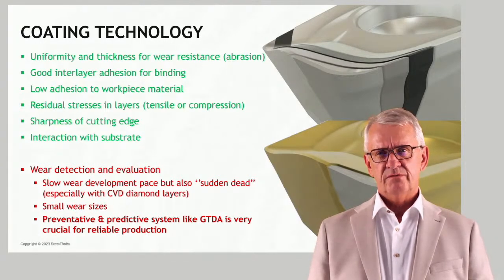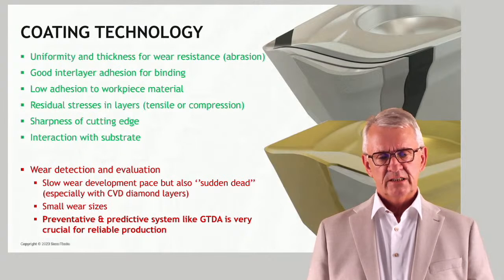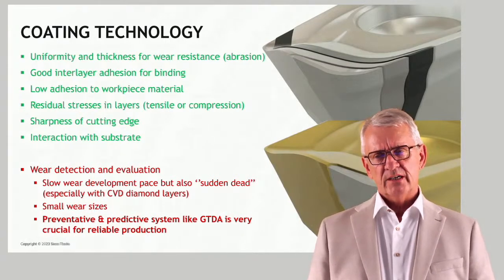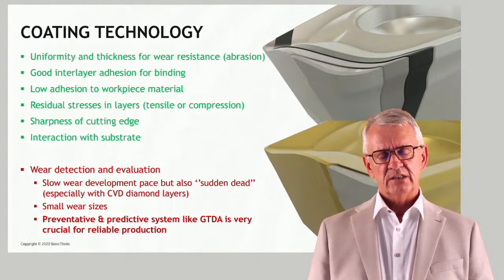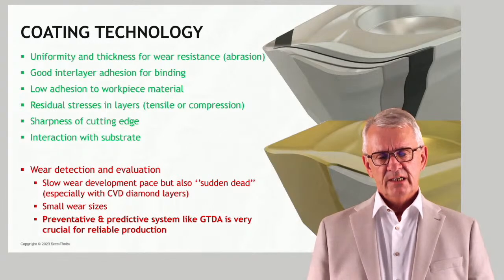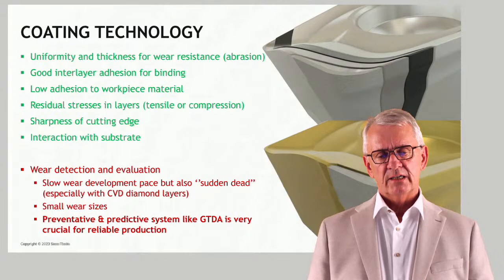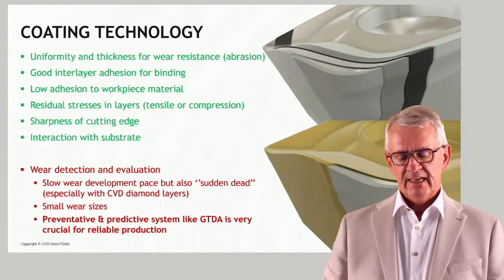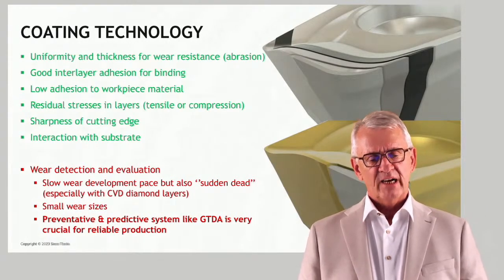Coatings. I'm not going to spend too much time because this is a subject on its own, coating technology. Today we have come so far in doing things with thin layers. It's incredible. But on the other hand, it has a drawback, and the drawback is that the wear resistance of these coatings is so good that there is nearly no wear appearing on cutting edges. It looks like it can cut forever, and then suddenly it breaks. And that is the drawback, that